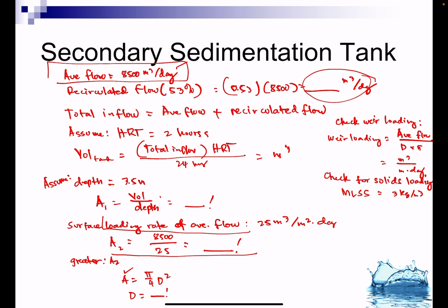Total inflow times the MLSS. So the total solids flow is equivalent to your total inflow times your MLSS. And that is given in kilogram per day.